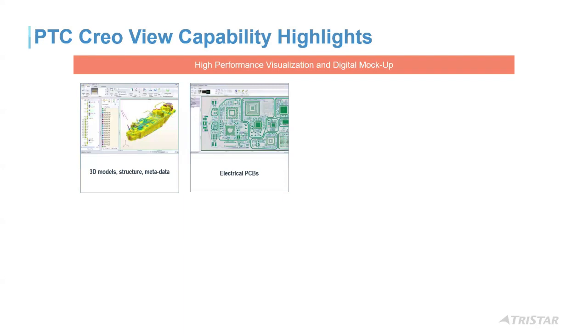There is also an ECAD component of this viewer. So just like the MCAD, the mechanical CAD, there's also the electrical CAD. So if you are creating things in printed circuit board design tools like Cadence or Siemens Xpedition or the Altium product or the Zuken product, you can actually visualize those, interrogate the boards, interrogate components, take a look at reference designator information, package information, naming information on components.